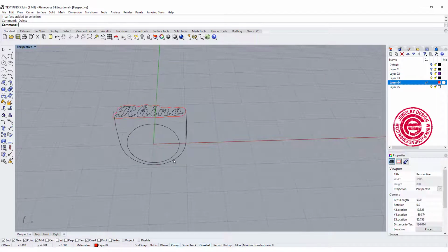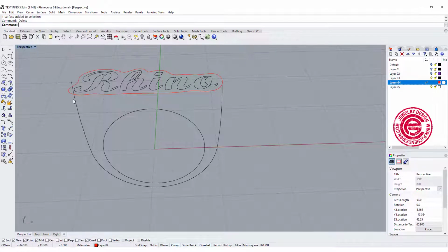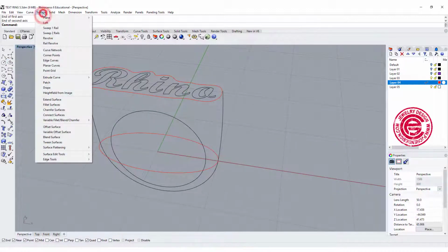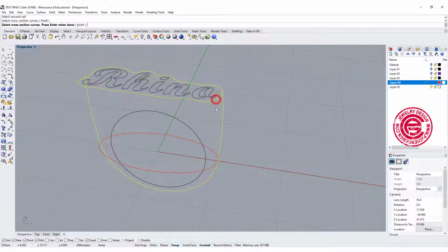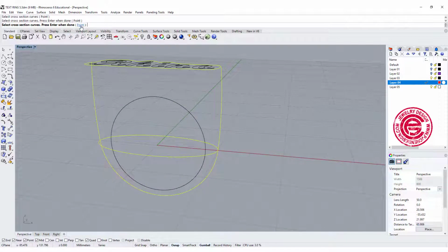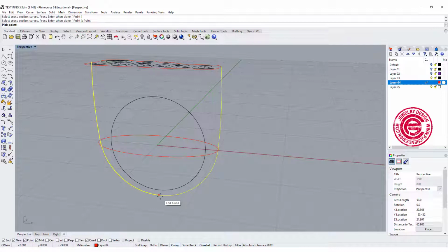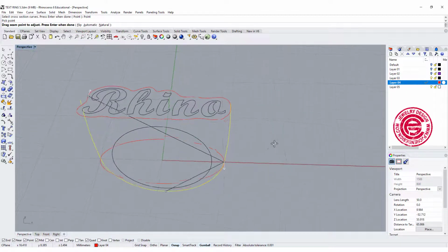I actually want my bottom to be nicer and smoother, more like a half round over there. So what I'm going to do is create another cross section, using the ellipse. We are going to do one more time the same command, sweep two, rail 1, rail 2, cross section, and we're going to come back to our option, click on the point, and snap into the endpoint or the quadrant. Alright, so this is what we have.